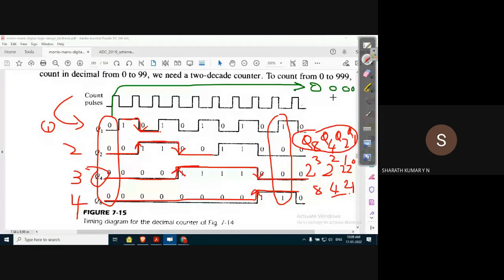As the clock transitions from high to low, the first flip flop will go from 0 to high, a rising edge. This continues. When it reaches the count of 9, there is 1001. The next state should not be 1010.